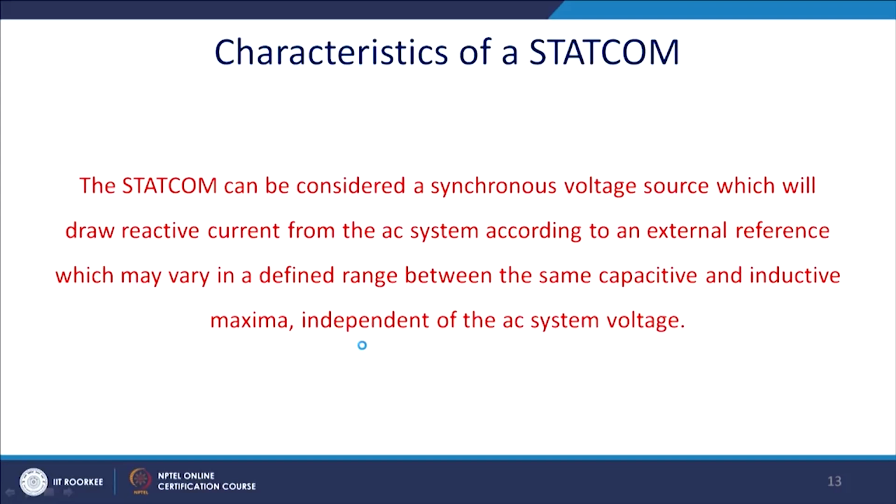So, what are the characteristics of the Statcom? Statcom can be considered as a synchronous voltage source which will draw reactive current from the AC system according to the external reference, which may vary in a defined time range between the same capacity, inductive and capacitive maximum, and independent of the system voltage.